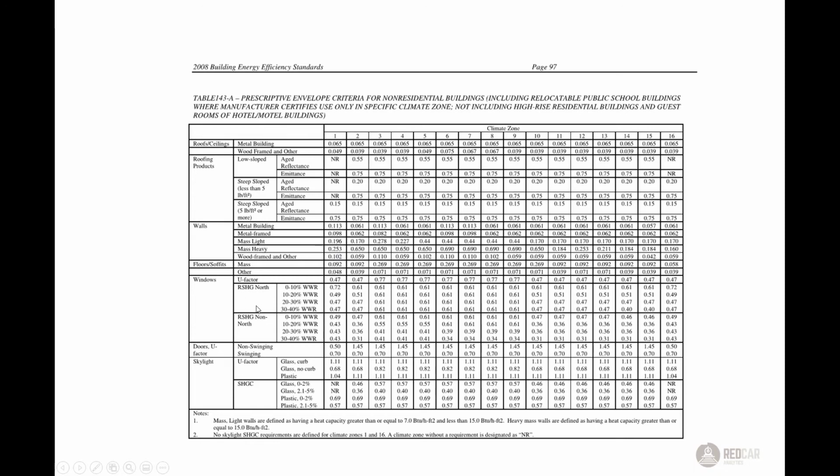And glass installed prescriptively in this climate must have this solar heat gain as a maximum. So there's different max and mins. They're all in the code, but the nice thing is a lot of these construction assemblies are already in libraries for you to quickly pull in the construction set for climate zone 2, and it gives a good starting spot.